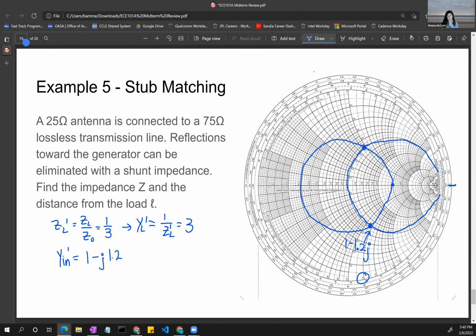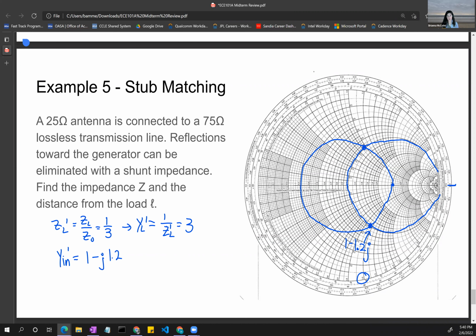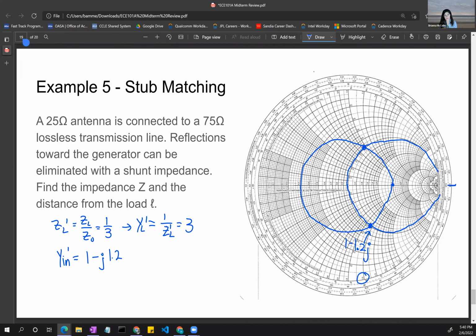So if we look at this expression, I want to explain why it's the closest one more time. So we're starting from the 0.25 lambda point and we're going clockwise around the circle. And so if we go clockwise around the circle, then the point that we get closest to first is this lower point, because to get to this upper point, we would have to go like 3/4 of the way around the circle. And that's longer than about 1/4 of the way around the circle. So that's why it's the closest point.